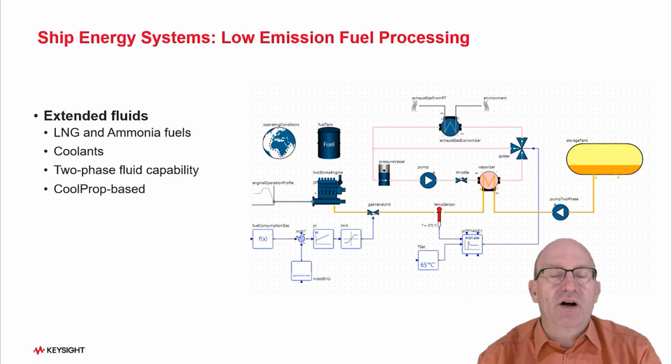Of course, it has an overall impact on the energy management on the ship, so you need to store it somewhere. And contrary to heavy fuel oil, you also store it in a compressed and cooled way. So that means you need to supply energy for cooling. You need to have a cooling system in your energy management considered, and you also need to transfer the state of the fluid because it comes as liquid from the tank. But if you want to burn it in your combustion engine, it needs to be in gas state. So that means there are vaporizers you look into, and these are, again, using energy and need to be controlled and monitored. And this is the purpose of our extensions to this ship energy system library.